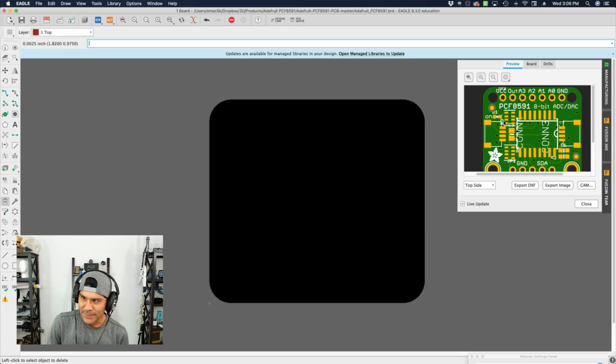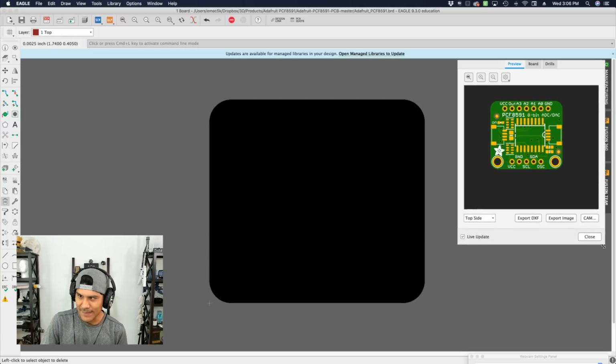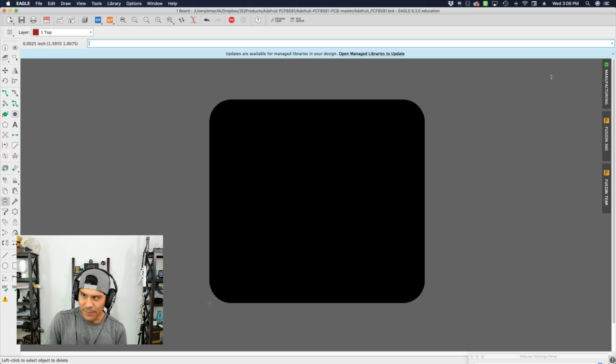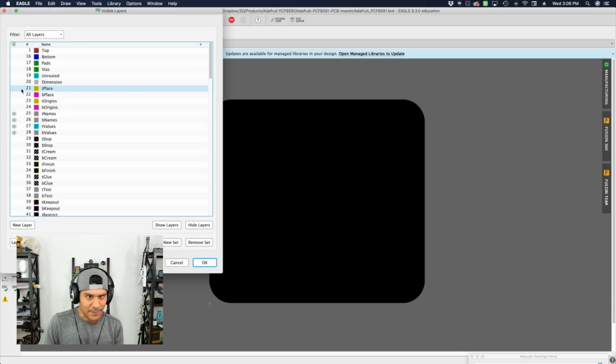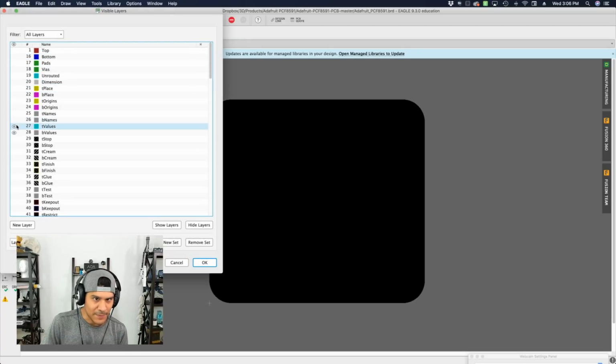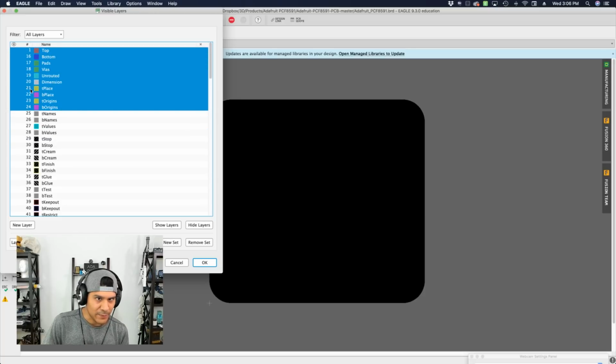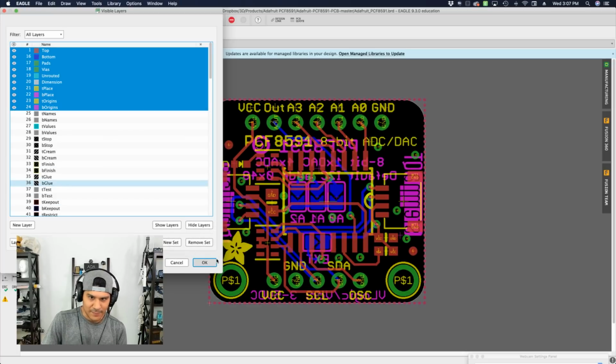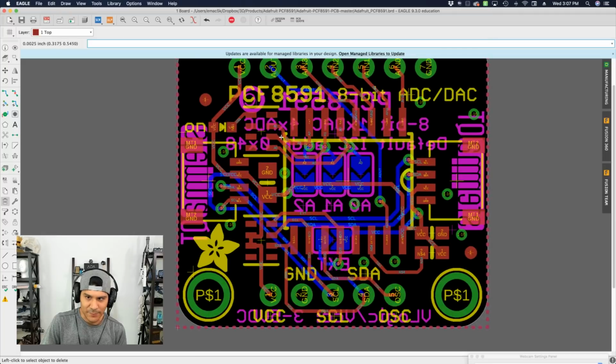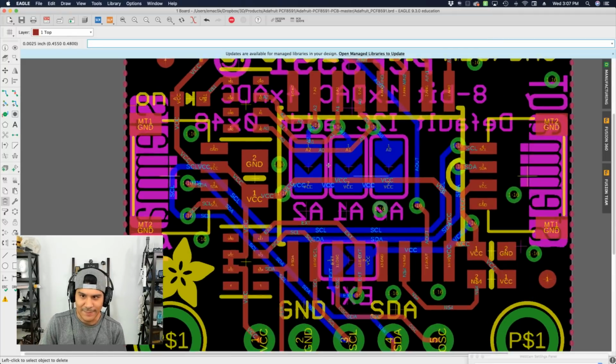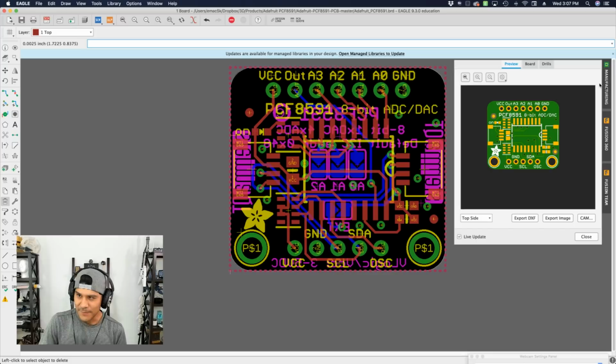So now inside the Manufacturing tab, all that stuff disappears, and all I'm left with is just the silk screen graphics and text that is in there. It really is going to depend on how your PCB is set up, but in this case, it uses the proper layers 21 and 23 to show the graphics. So here's what everything looks like all at once. It's a lot of stuff, but if we look at the Manufacturing tab, it's the right way it's supposed to look.